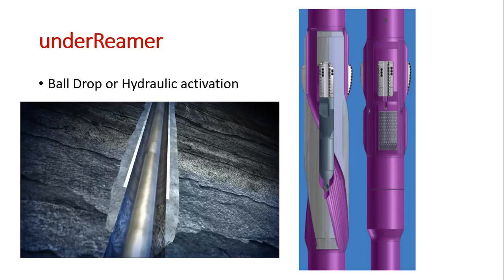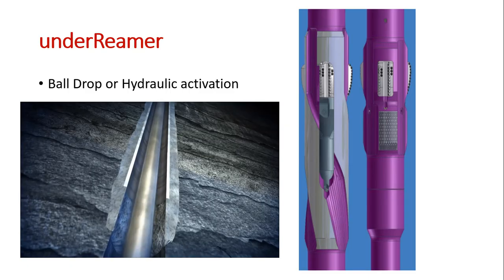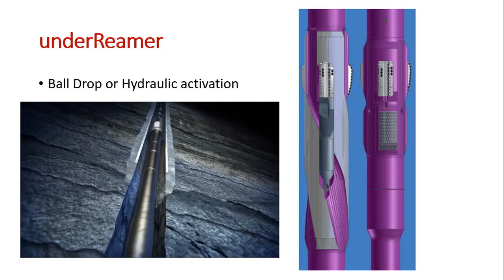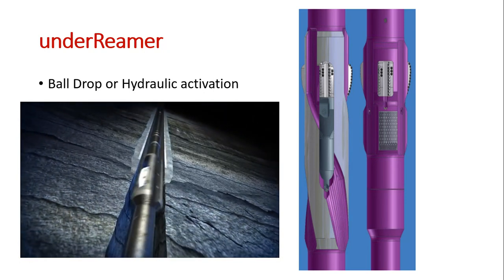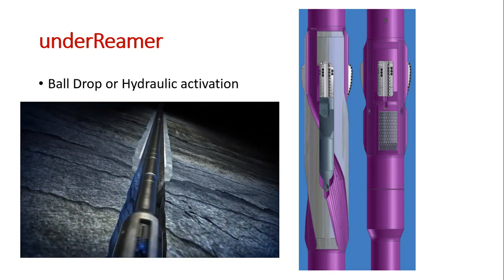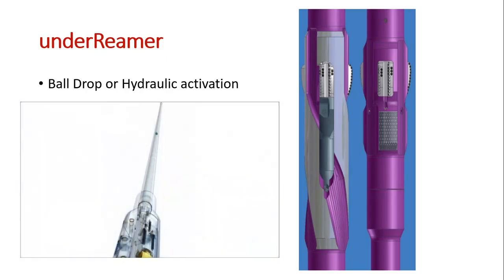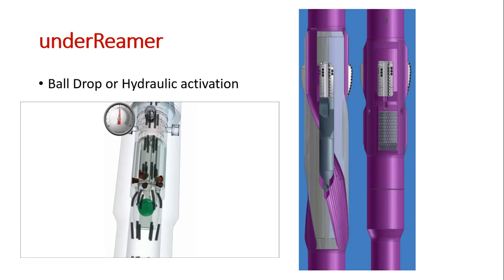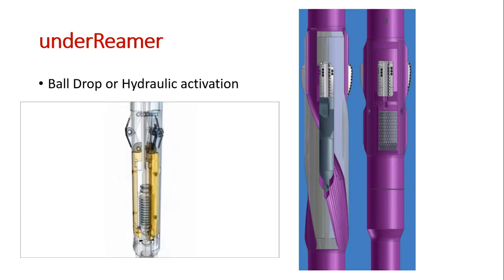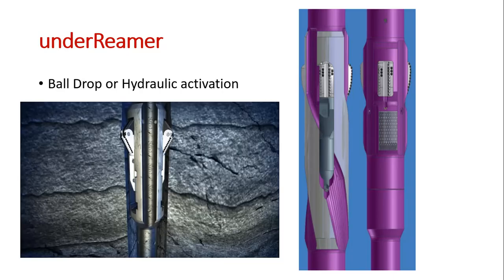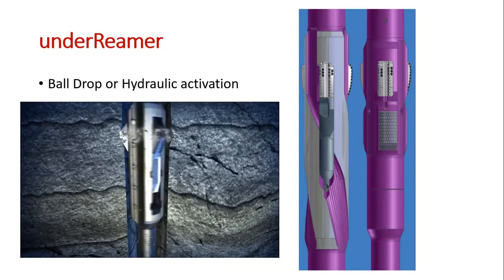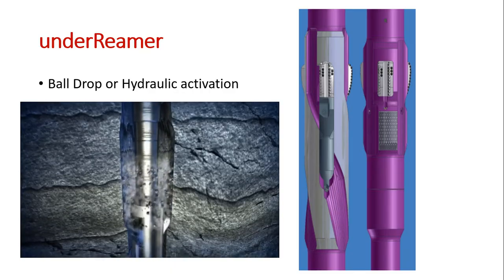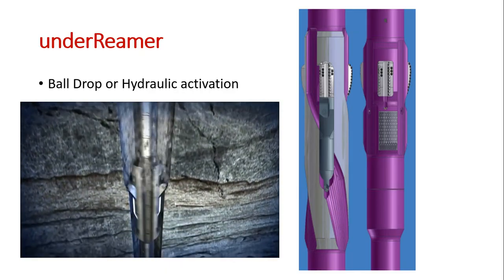The casing shoe and cement are drilled out conventionally, with the under-reaming tools being dormant to ensure that activation in the casing does not occur. Drilling of new formation continues until the XR reamer tool is below the casing shoe. A ball is dropped and pumped down, which activates the XR reamer and allows the arms to open. Once the XR reamer cutter arms are fully deployed, simultaneous drilling and reaming commences until TD of the section is reached.